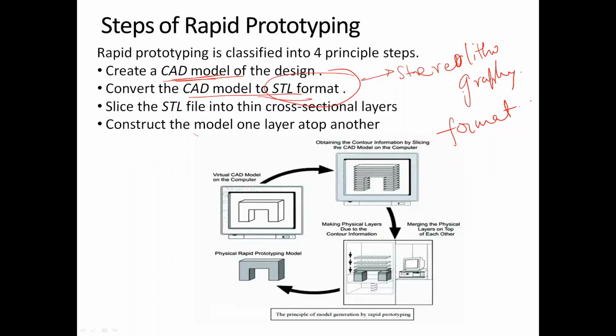So the format that came along with that machine got to be named stereolithography format, and the short form for that was STL format. So that is how it started. It's a very simple format, so it became a de facto standard for all the machines and softwares related to additive manufacturing to possess this feature.